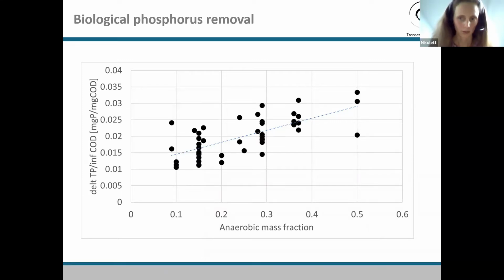So this is considered for the dynamic simulation. So we take into account the daily flow fluctuations and the temperature variations throughout the year. Why is it also important to have this? Because that yearly simulation is used to get the maximum airflow rates for the blowers, for example. So this means that all of these factors are taken into account.